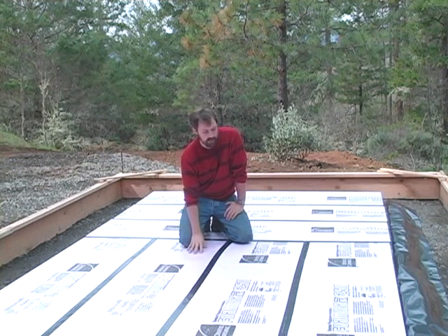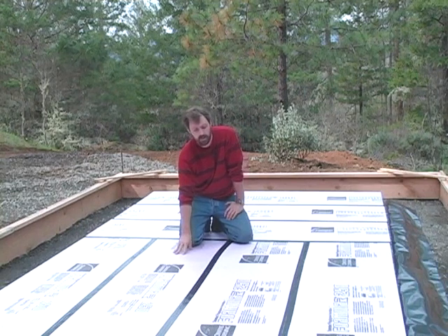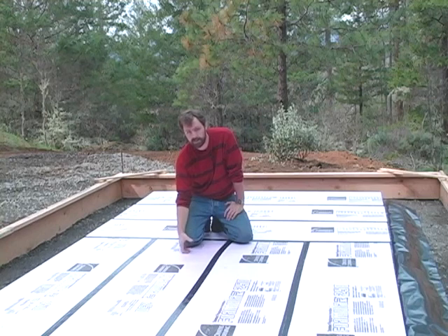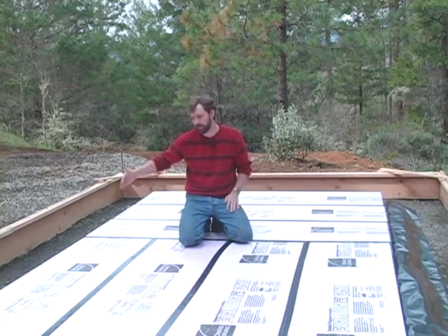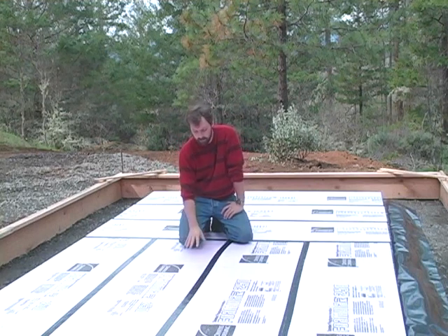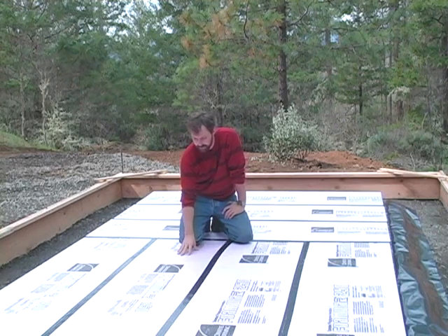Now on top of the plastic, I've placed 3 inches of rigid foam insulation. It's important to use the extruded polystyrene insulation, which is rated for structural insulation. It can be placed underneath the slab. There are other types of foam that are designed for vertical installations along footings and edge walls, but they're not designed to hold the weight of the concrete on top of them. And once I've installed those at 3 inches, I'll have an R15 value underneath my slab.